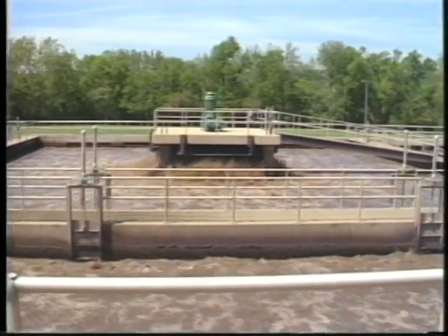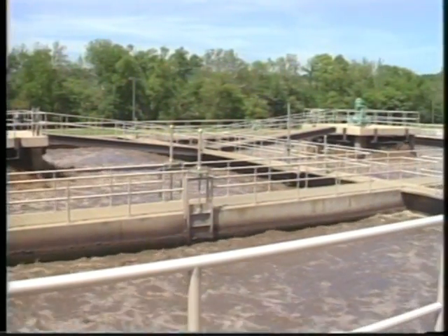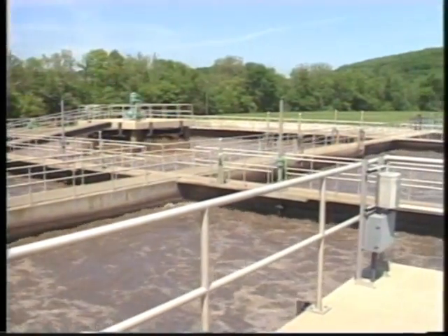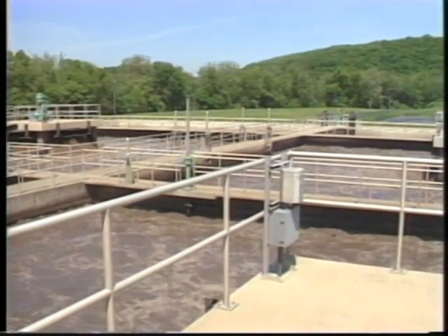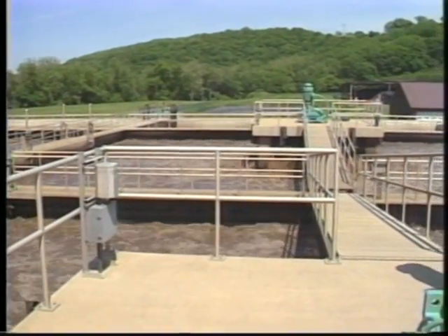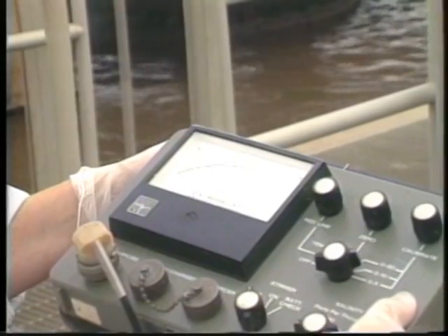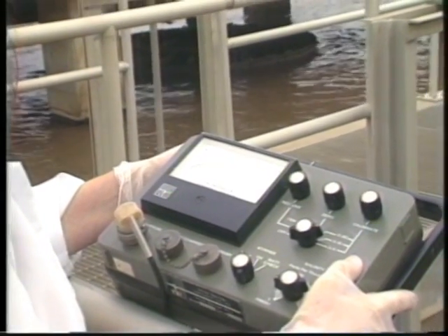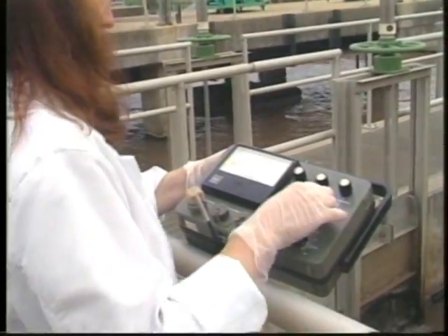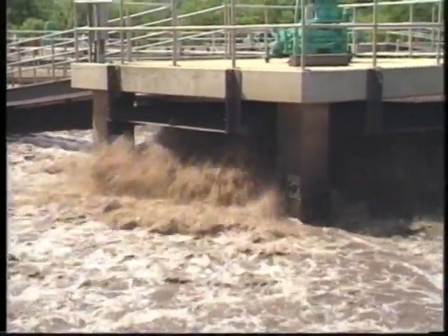The step feed system may look very similar to a conventional activated sludge facility. In fact, with step feed, there is a great deal of flexibility and it can be operated as a conventional or even in a contact stabilization mode. When operating in the step feed mode, the influent wastewater is distributed at different locations through the course of the aeration tank. This mode of operation distributes the oxygen-demanding pollutants throughout the entire aeration tank as opposed to concentrating it at the inlet end of the tank. This helps to reduce oxygen sags in the aeration tank.